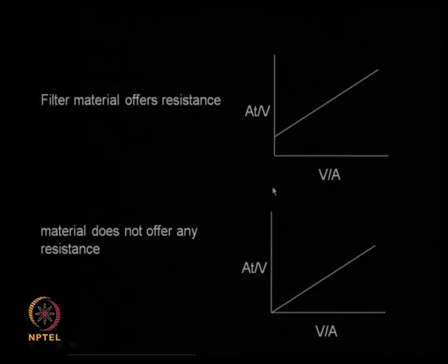So we saw different situations. We took Darcy's law, and then we said velocity of flow is equal to 1 by A dV by dt. Capital V is nothing but the volume of liquid that needs to be filtered, so dV by dt is the average rate of filtration. On the left hand side you had the velocity, and then we had Darcy's law incorporated into that.